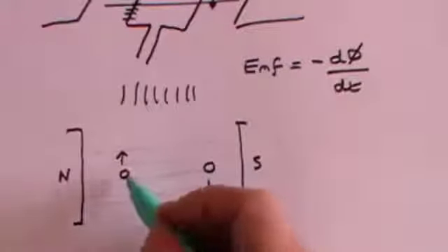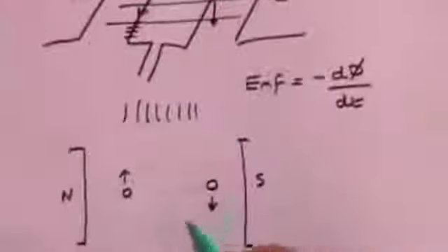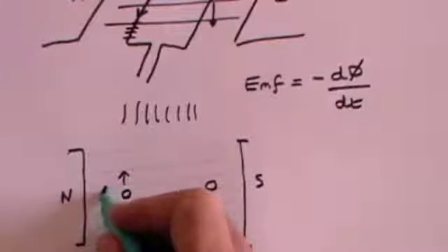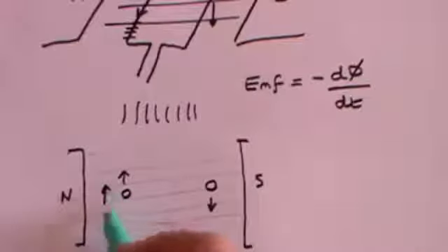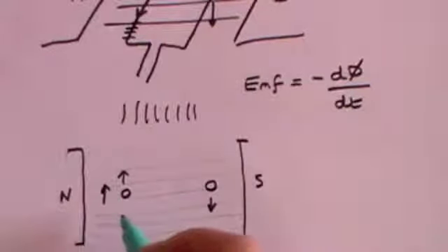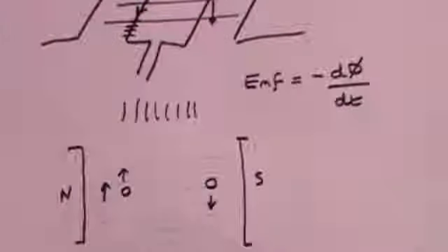As it is moving around in a circle, because the whole thing is looping, for the time being, when it's in this position, it is moving across the flux lines. Consequently, it is cutting the flux. It's the maximum point at which it cuts the flux, and therefore it generates the maximum EMF. So if we plot